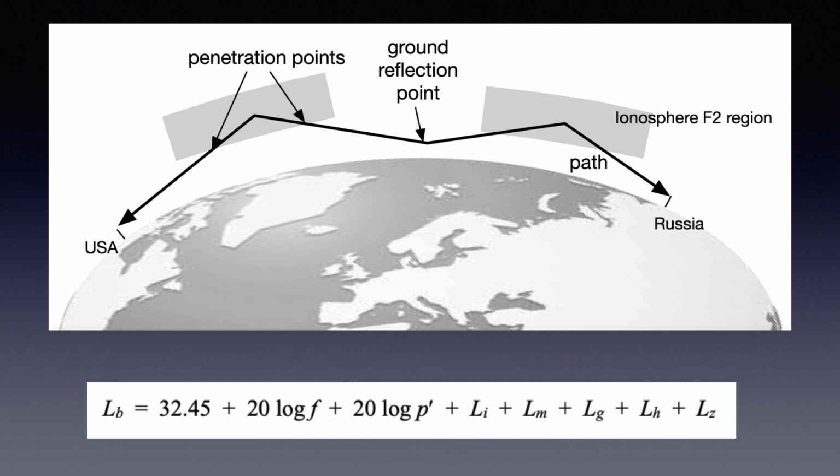Remember of course that the path loss is the median, and if we're prepared to accept a lower chance of success, more path loss can be accepted. Also remember that even if the dBs add up to something that will work, the local noise at the receiver may degrade the threshold to something unworkable. Local electrical noise is significant at HF.